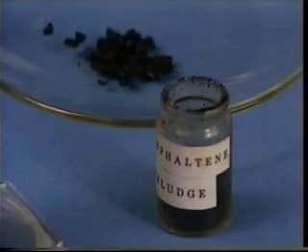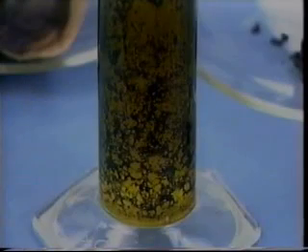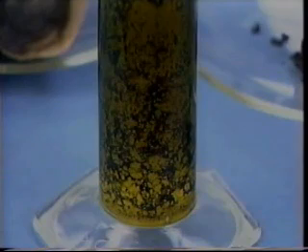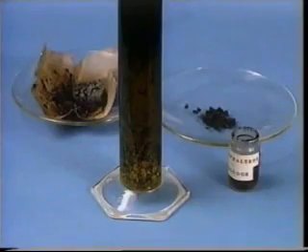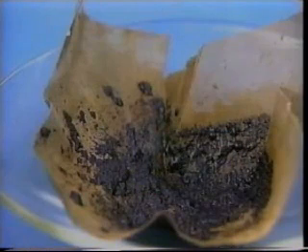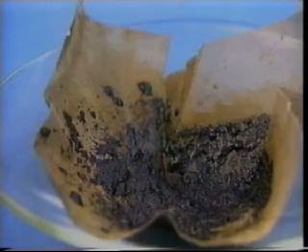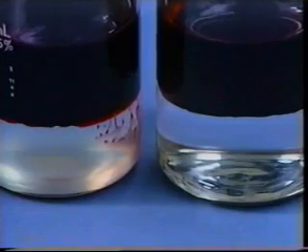Surfactants can sometimes minimize sludge problems. Sludge is a solid that forms when acid contacts asphaltic crude oil. Sludge is extremely difficult to dissolve and will adhere to reservoir rock, causing a decrease in permeability. Surfactants can also alter reservoir wettability.